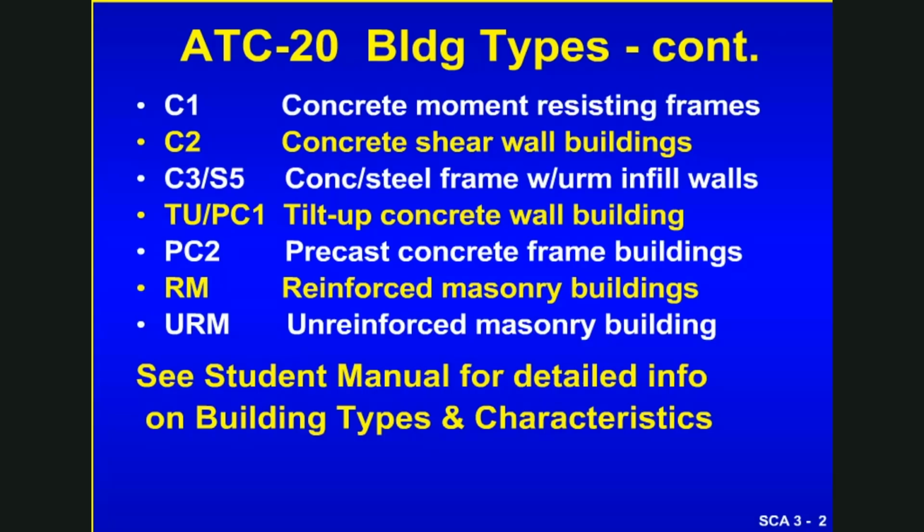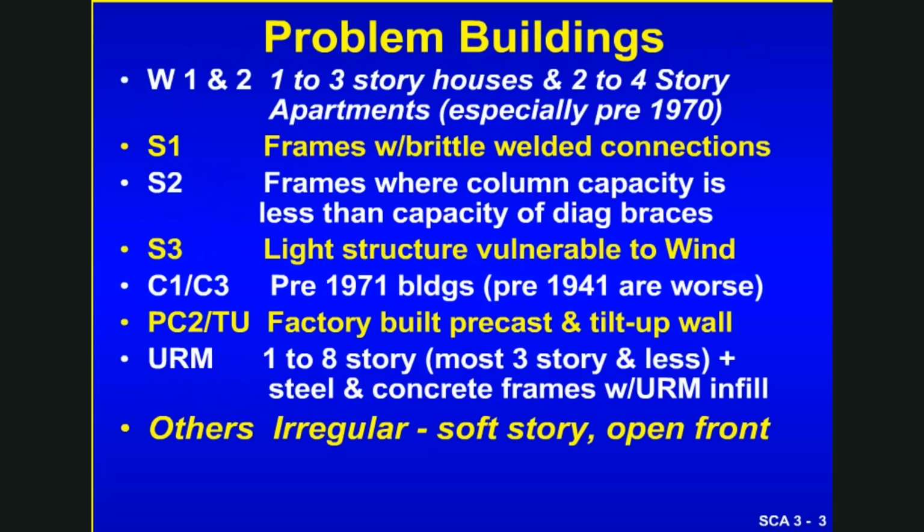In your student manual, you'll find detailed information of all these structures regarding their characteristics, as well as how they behave when subjected to extreme loading conditions. Problematical buildings are, or putting another way, most buildings when subjected to extreme loading have been problems. The only one that you won't see on this slide is the C2, or concrete shear wall type building, which behave probably better than most others for almost any kind of extreme loading you can think about.